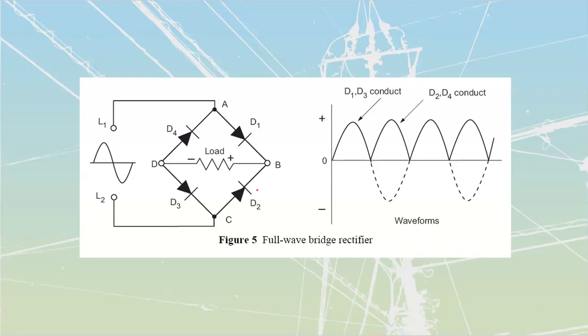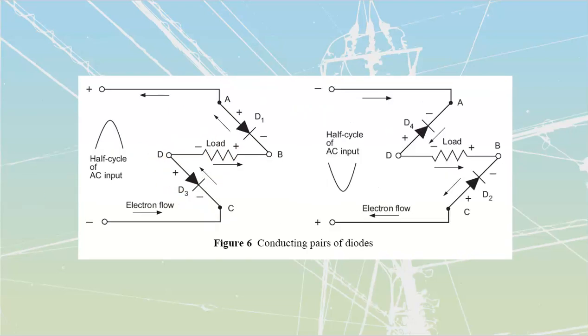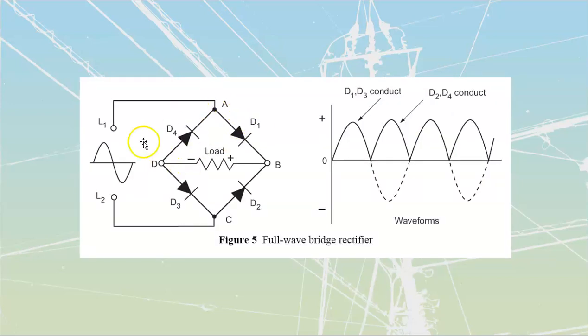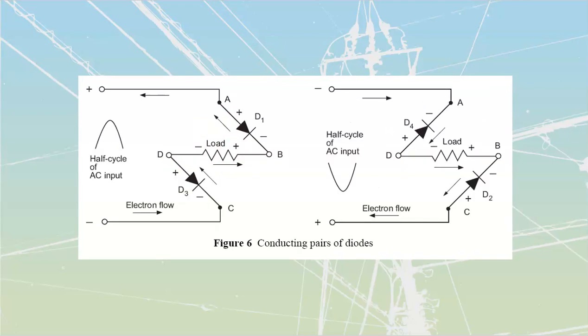This is a bridge rectifier. A bridge rectifier is going to have pairs of diodes that are going to work in tandem together to pass current through. And they give us a very great visualization of that. They actually cut away the ones that are not conducting. So these diagrams that they have over here show the conducting pairs. They're just ghosting the other ones that we would normally have across here and here. They're just not showing them so that we don't have to analyze them at any given point.